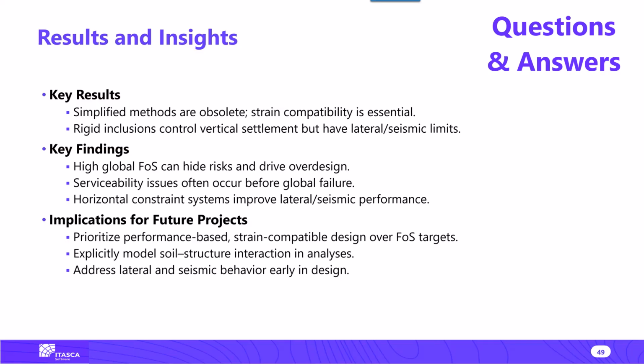The wall face was linear. And in that case, each panel was modeled independently because those panels are not a continuum concrete wall. Those panels have joints, are separated, and there are leveling pads on which each panel is sitting on top of each other. So you have to be able to capture those discontinuities, because if you model it as a single concrete element from the foundation all the way up to the elevation, you get a completely different structural stiffness, bending capacity, and shear capacity than you would get from the real discontinuous structure.